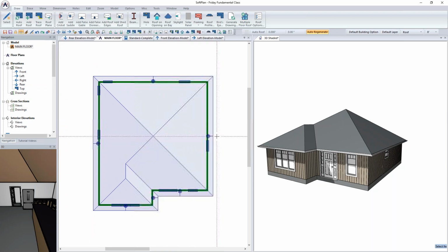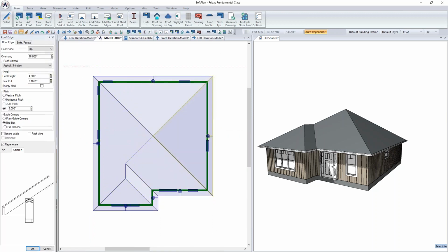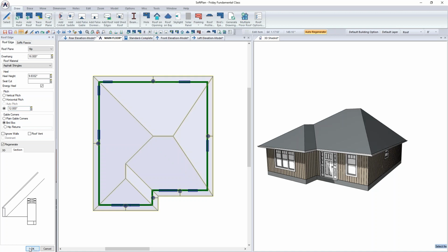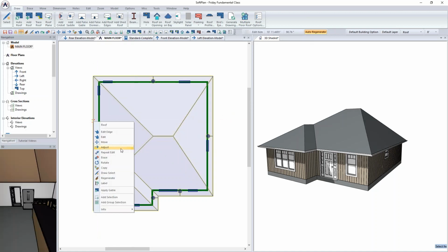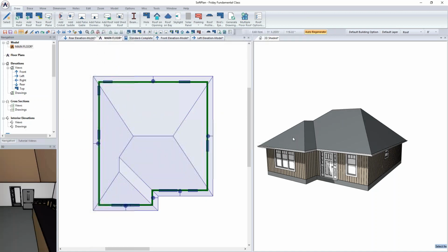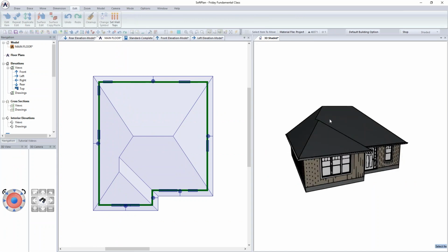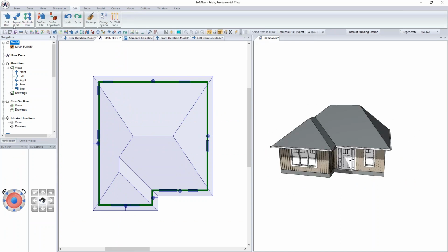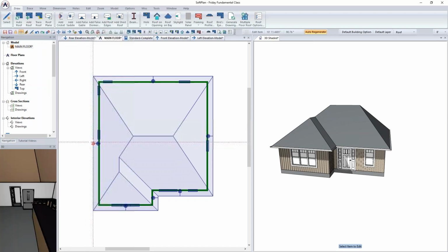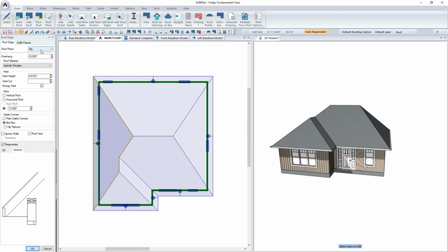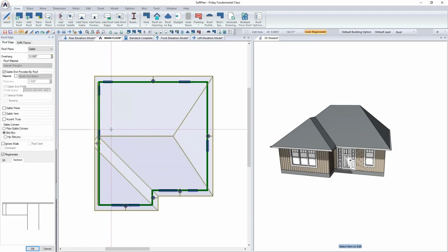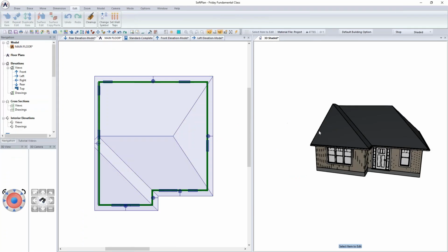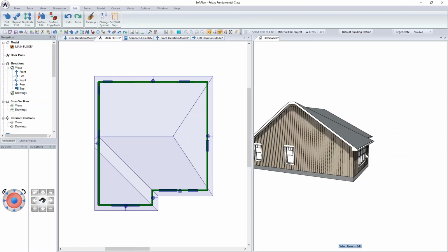So, for example, editing this edge of the roof over here, I could change that overall roof pitch. So let's say a 12/12 pitch. And when I come over here, I can do the exact same thing with the repeat edit, but it does change it all the way down, both pitch and the style. So keep in mind, if I were to edit this edge over here and try to change that to be a gable, in the same way I did the pitch, the gable now runs all the way from one end to the other.